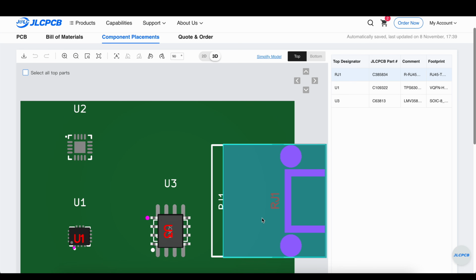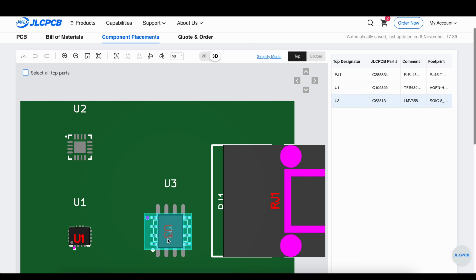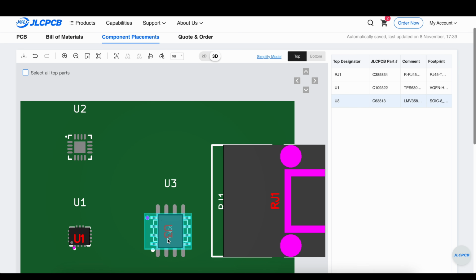So frustrating. So how do you fix this? Well, the Fabrication Toolkit does have a custom field that you can put on your symbols and on your footprints that will override the position and adjust it so that when it generates the position file, it will get things right. It is a manual override, so you have to come in here and figure out the number of millimeters to offset things or the number of degrees to rotate the component. It's a process of trial and error, and I've already figured it out for these components. You'll have to do that on your own just by observing how many degrees you have to rotate it.